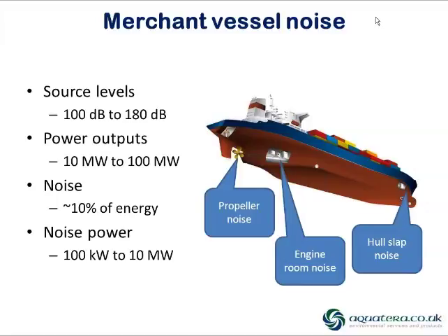What's interesting also to reflect on, I think, is the power of the engines that are involved in propelling these types of vessels. And if we convert those power outputs to megawatt equivalents, a large merchant ship might have 10 megawatts or 100 megawatts of power being emitted from the propeller. If perhaps, and this is for the sake of argument, 10% of that energy is transmitted into the water as noise, then the noise-power relationship would be somewhere between 100 kilowatts and 10 megawatts. And that's quite a considerable amount of noise-related power that's going into the sea.